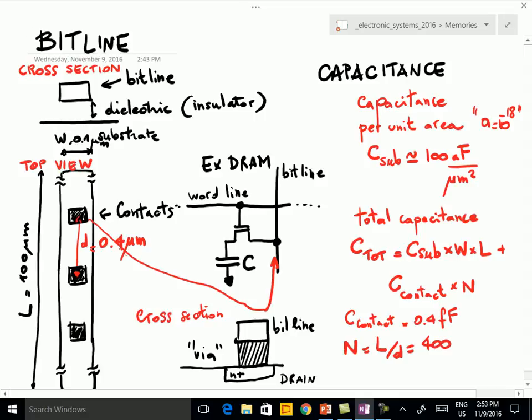And then if we make this calculation, at this point we have everything, we end up with something like C tot equal 101 picofarad. Okay, so femto means 10 to the minus 15, and pico, of course you know this, it's more common, means 10 to the minus 12. So 100 picofarad, more or less, which is not small.